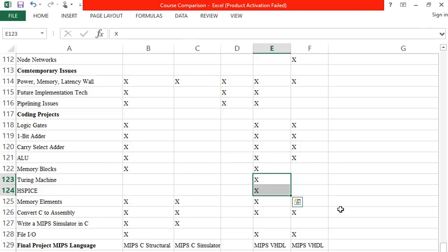However, the reason why I don't think that's an appropriate project for an advanced digital systems course or for this type of course in general is because it's still doing A plus B, it still disassociates what is actually happening at the digital level, right? So A plus B, well, congratulations, you knew how to add in kindergarten, right? Because you're not learning anything new. Whereas with you guys, you designed an AND gate, OR gate, XOR gate, then you made an adder, then you optimized the adder, and you put it into the ALU, you made a comparator, you did OR gates and NOR gates, you did a multiplexer, and you made your freaking ALU.